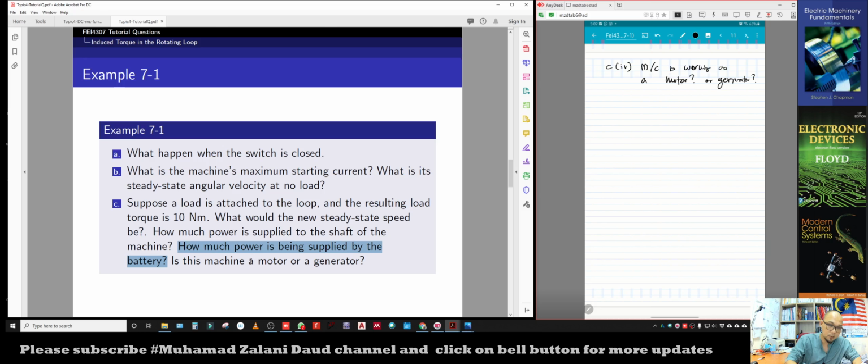Okay, the machine is working as a motor or generator. We can say that if VB is larger than the induced voltage, this is a motor. But if E_in is larger than VB, then this machine is working as a generator.